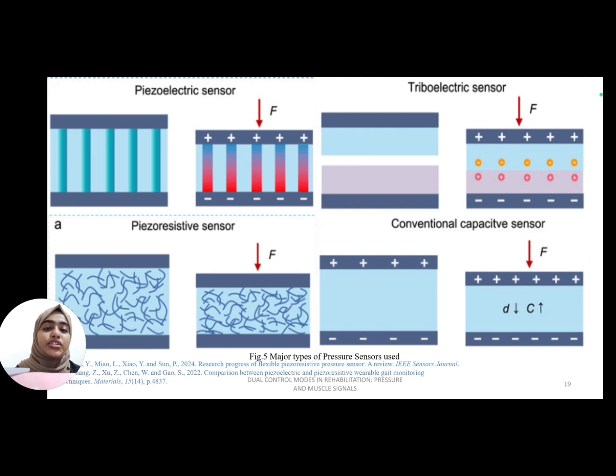The disadvantages of piezoresistive sensors are that they drift with temperature and have limited sensitivity at very small forces, which led to the development of capacitive sensors. So next comes the capacitive sensor.